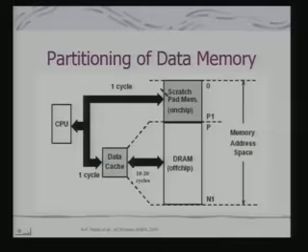In terms of access speed, your scratch pad memory should typically be synchronized with a one cycle access, that is the same clock cycle as that of the CPU, so that accessing this memory does not need wait states. In case of DRAM, we have shown here typically 10 to 20 cycles, so it might require wait states, and that is why that memory is expected to be mapped onto the data cache depending on your cache management policies.